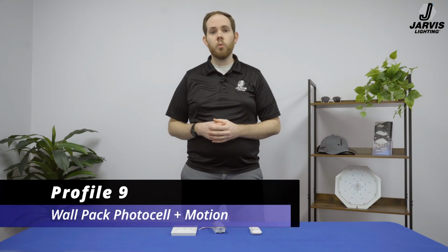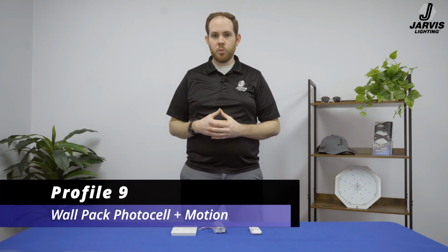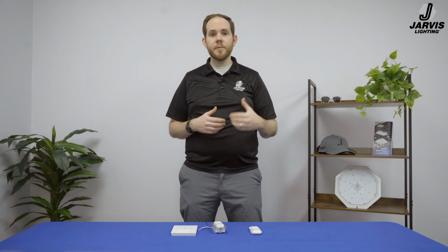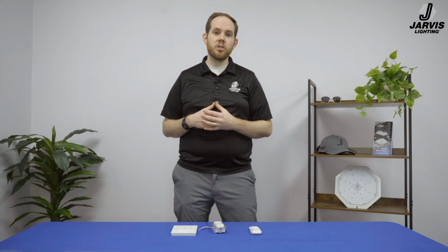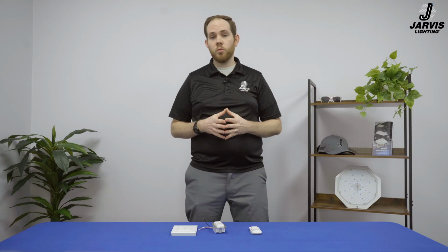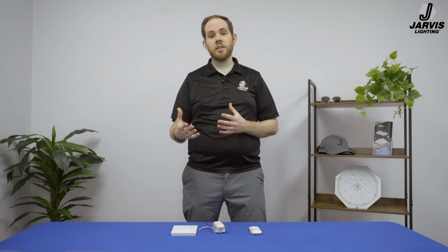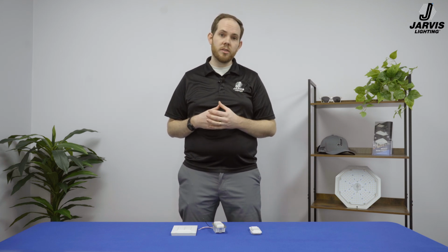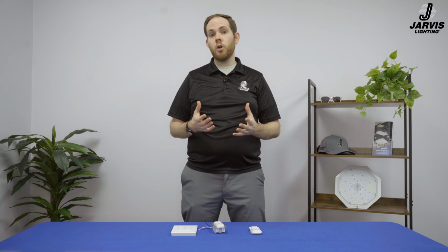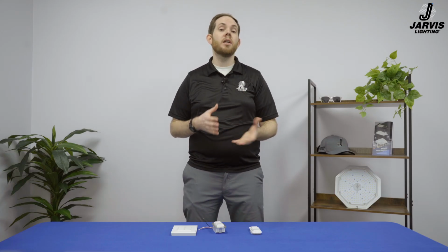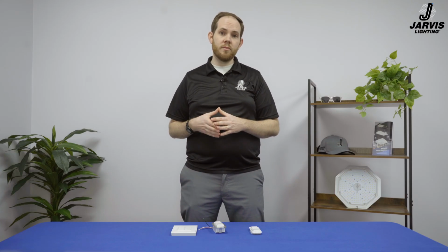Profile 9, our wall pack photocell and motion profile, features the same photocell settings as Profile 8 with similar occupancy settings to Profile 7. The fixtures in a zone assigned this profile will turn on at 30% brightness at dusk. Then if motion is detected, they'll increase to 100% brightness. And after 15 minutes of no motion detected, they'll return back to that 30% brightness level. Lastly, they'll turn off at dawn.